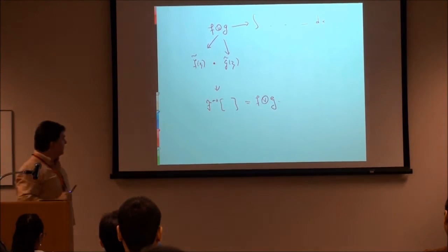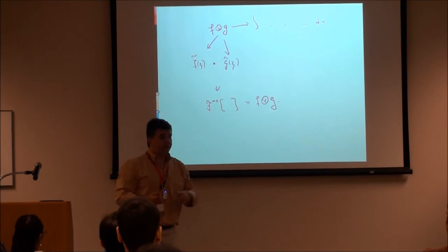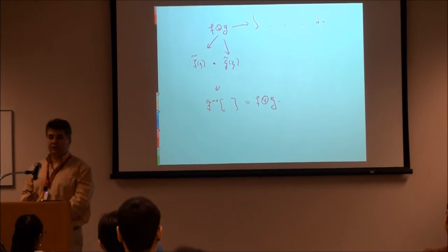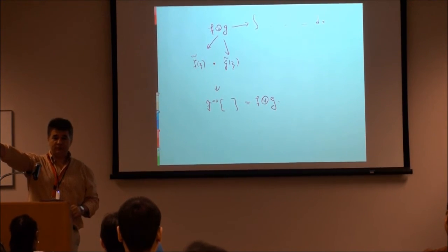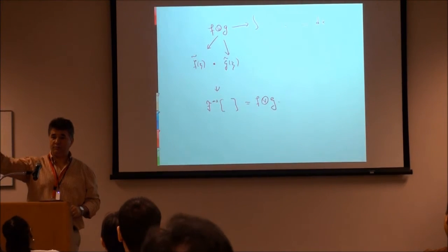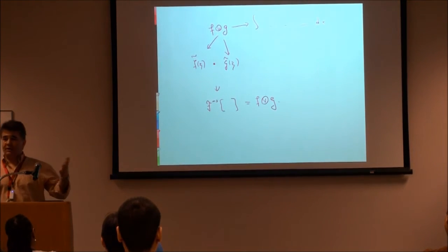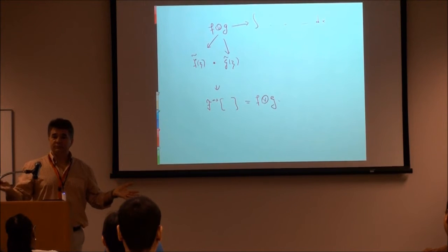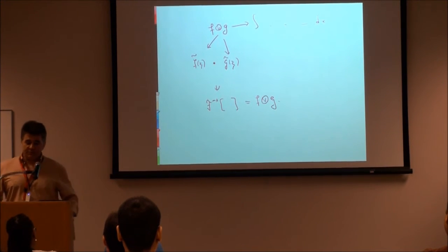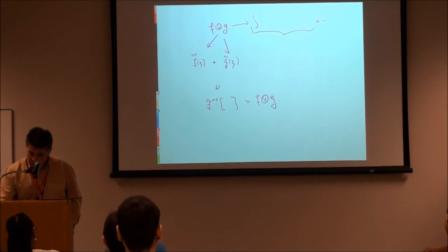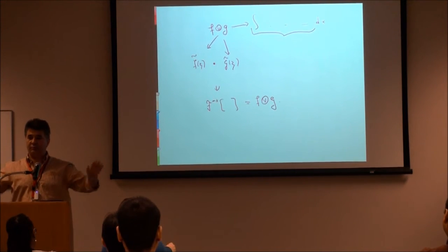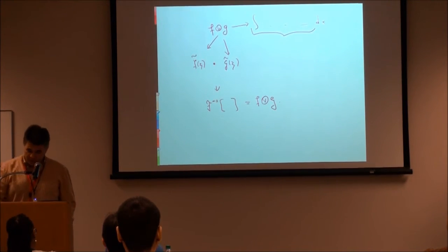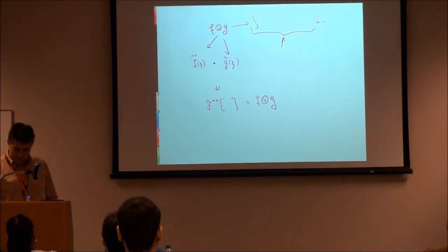That's something. Why? Because now our computers are very efficient in doing Fourier transforms. So if you give me a random input that I know is going to come to my system, and I know the impulse response of the system, that output is going to be a convolution. Okay? So I have two options. I go do this integral, or I take the Fourier transform of the two, multiply, Fourier transform back, and I can bet you a coffee it is going to be much faster this way.